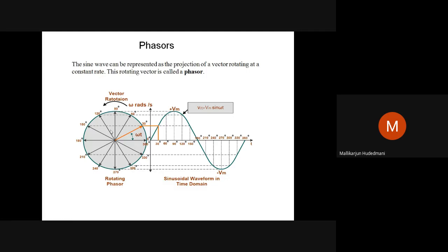When a vector is shifted by an angle omega t, this is nothing but a position on the graph. A shift of 30° means the vector took up an angle of 30°. What is the magnitude available here? On the graph, you touch it here and read on the vertical axis. But this graph is not there with you. How do you read it from the rotating vector? For that, we have to imagine this particular vector with a torch put from this side: the projection of this along the vertical axis.